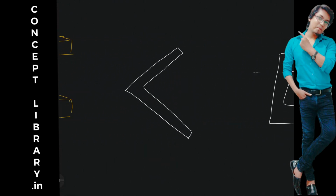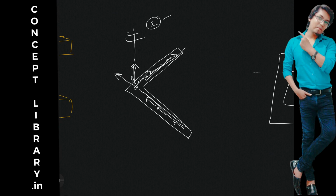Suppose you have a channel here and you have shear stress flow like this. At this point, one was in this direction and one was in this direction, correct? So the resultant of both will be in this direction. Now I am saying apply any external load. This load has to take care of two things. One, the resultant shear force coming from this and this should vanish after the application of this force. I mean the total resultant force after applying this should be 0.